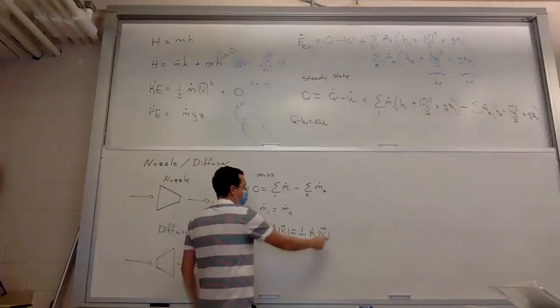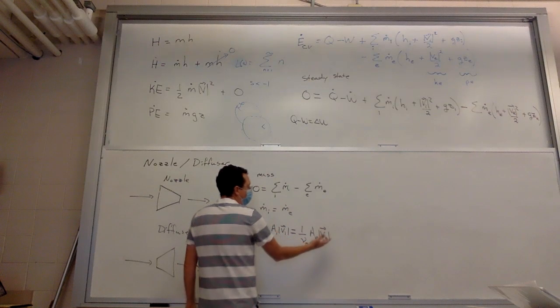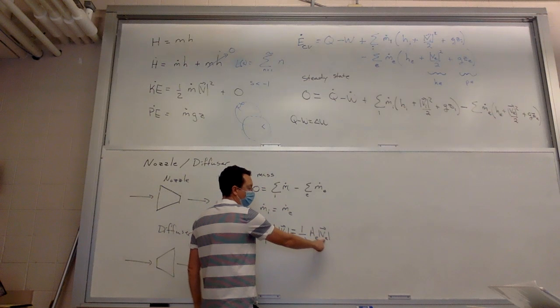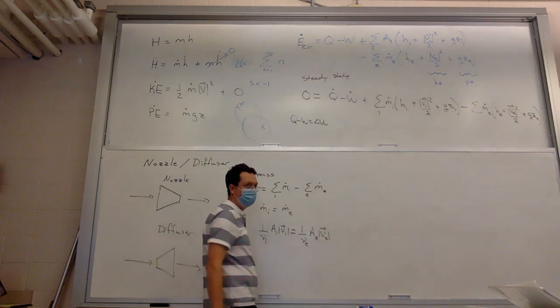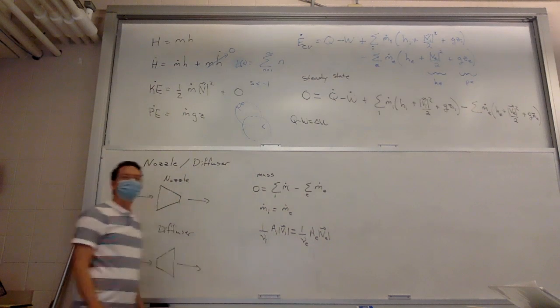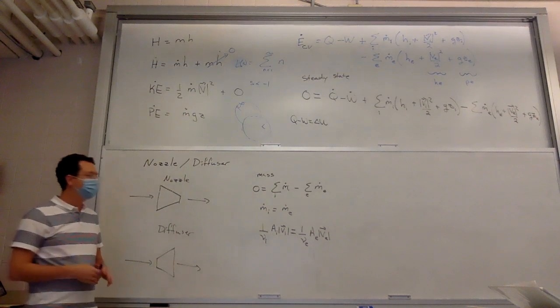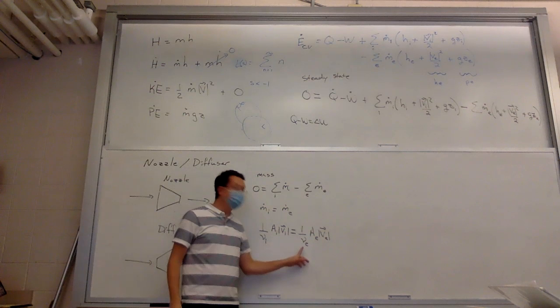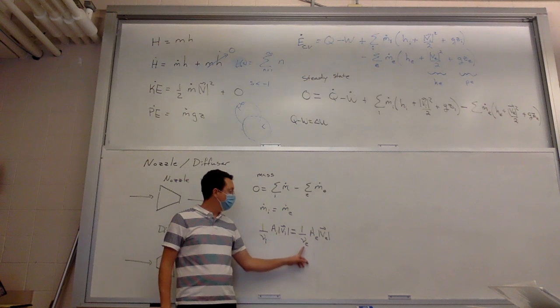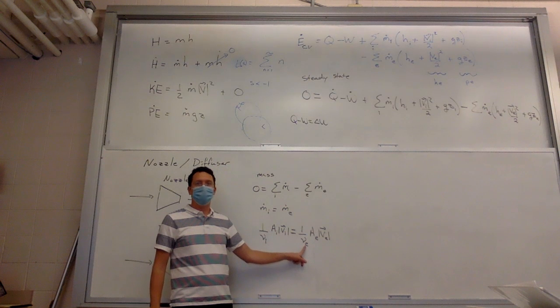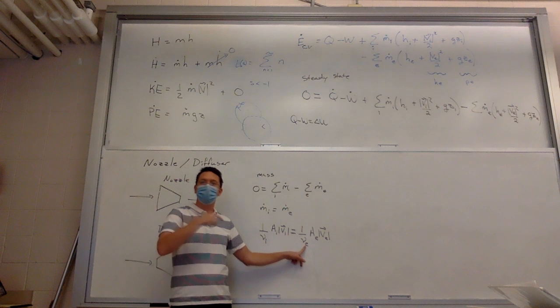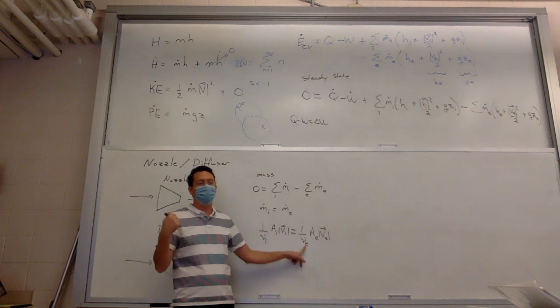And that means, in particular, you would expect typically that if the area decreases, the velocity increases. So if one goes down, the other goes up. Now, in reality, it's a little more complicated than that because you could also try to compensate by adjusting the specific volume. It all has to do with knowing the temperature and pressure at the input and exit.